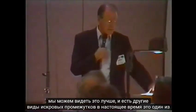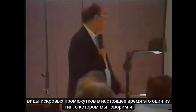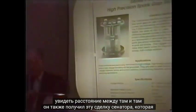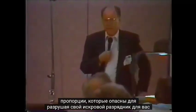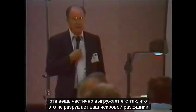And there are other kinds of spark gaps. Now, this is one of the type that we're talking about. See the spacing between there and there. It's also got this center piece, which prevents an overflow if you reach proportions which are dangerous to destroying your spark gap. That partially unloads it so that it doesn't destroy your spark gap.